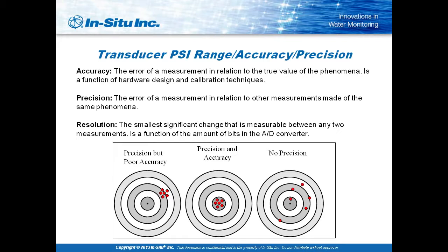The USGS, for instance, when they calibrate an instrument, calibrates it across the entire temperature and pressure range. I think this is necessary to understand, because if you're calibrating to 3 points as opposed to 20 points, obviously your calibration when you're doing it to 20 points is going to be a lot tighter and a lot closer. So when you are selecting an instrument, I think it's necessary to make sure you understand how they've calibrated that instrument. Otherwise, you really don't know the accuracy of the data.